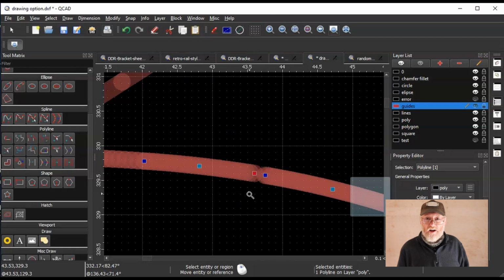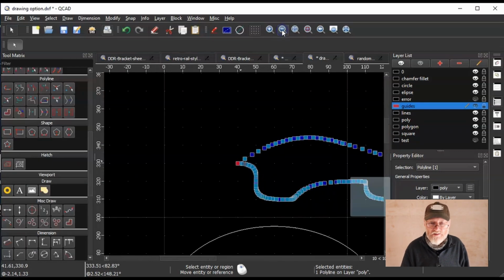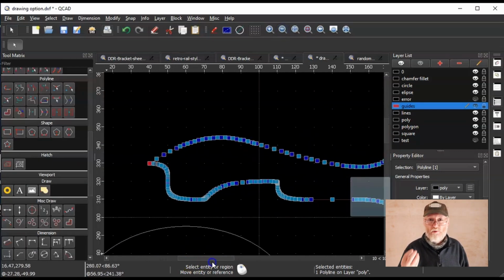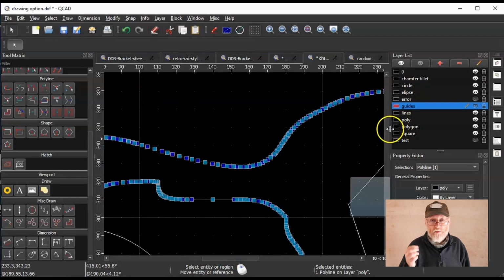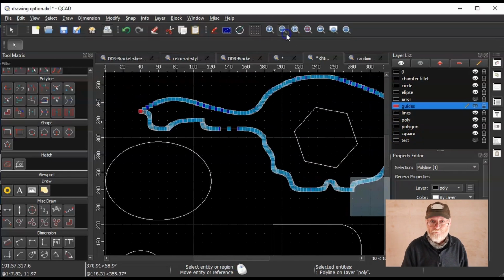Now then, within the part I've also hidden another couple of elements to show what else can also happen as you're creating these things and editing them. There's something called zero length entities. These could be just a simple dot on the screen that appears randomly, but that could be enough to throw out the software using the CAM.